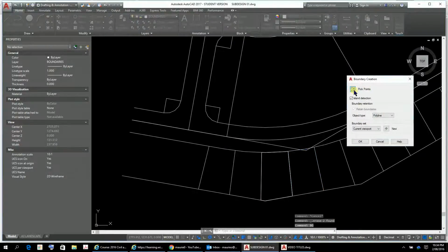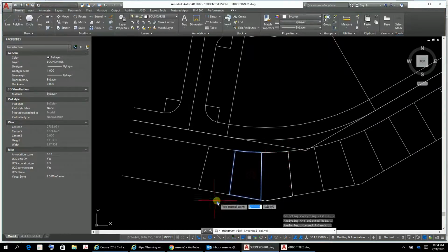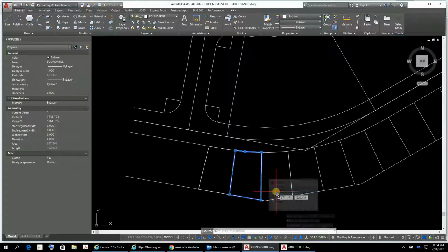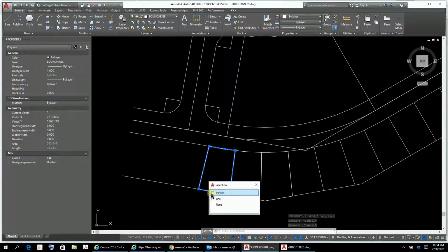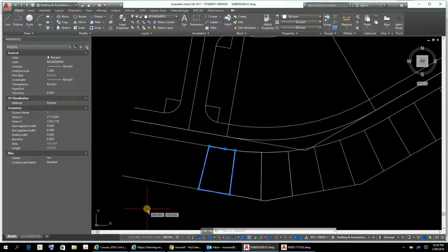Okay, pick point there and there, enter. Okay, so we do then together that one there, polyline, we get 617, so that's all good. And this one here, polyline, it might be alright there, 592. So I'll probably make that one there, seeing we're past the tangent point. 592, we need to add another 6 meters at 30, so that's probably another 0.2 onto that there, which is pretty simple.